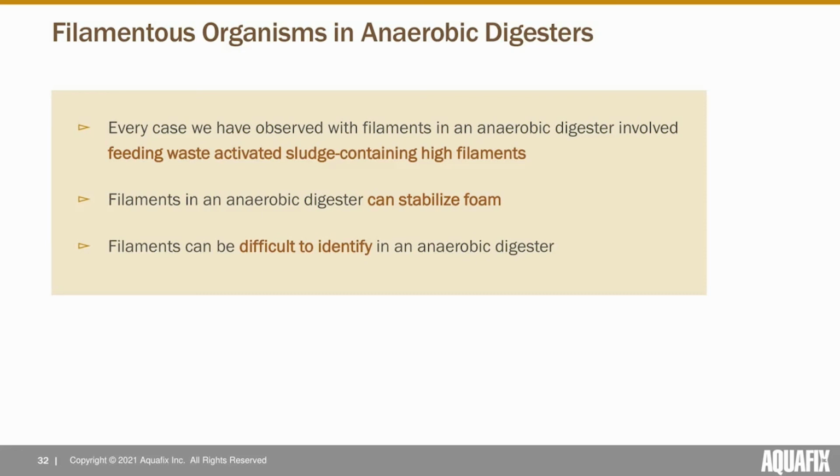But some of the filaments, particularly Microthrix, can perform some limited metabolism, it looks like, and at the very least can survive dormant in a digester for approximately a month in a mesophilic digester, which is plenty of time for them to accumulate and cause a foaming event. The nice thing is these filaments are generally not going to grow in the process, which means you can look directly at something like waste-activated sludge or another feed substrate and say, that's where these filaments are coming from. I need to address the problem at that point rather than have it feed into the process.